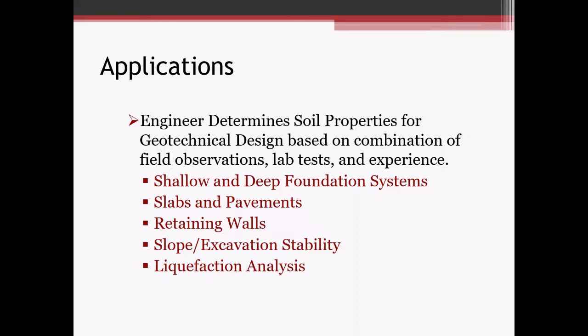For retaining walls, we evaluate the foundation soils, as well as the soils that will be retained by the wall. For slope stability and excavation stability, that's typically performed before, during, or sometimes after construction, or after there's an existing slope failure. And then finally, liquefaction analysis determines the potential for the site soils to liquefy during a design earthquake event.